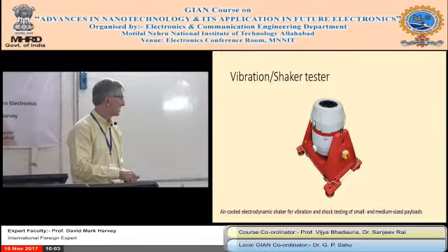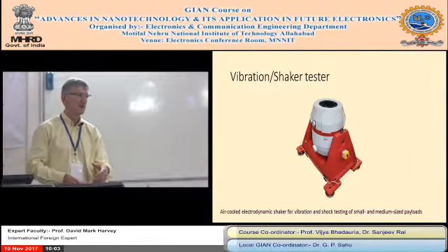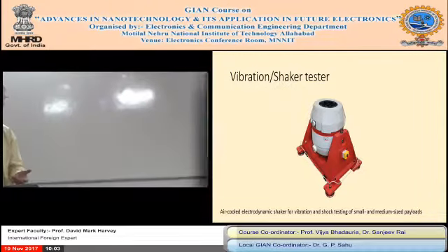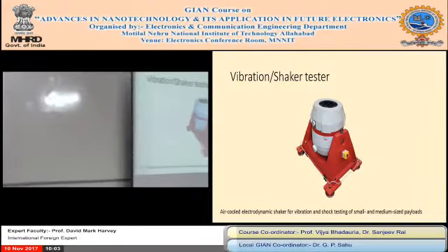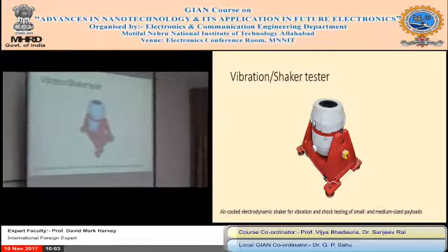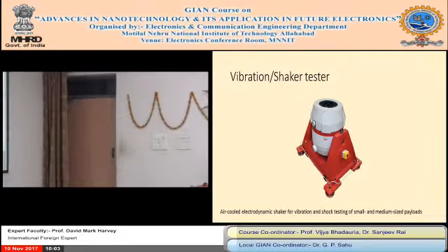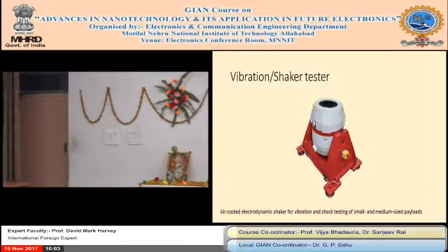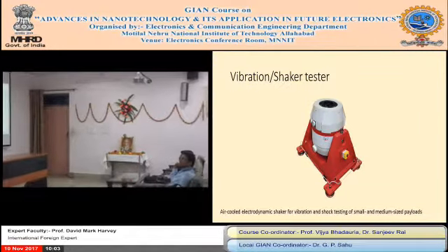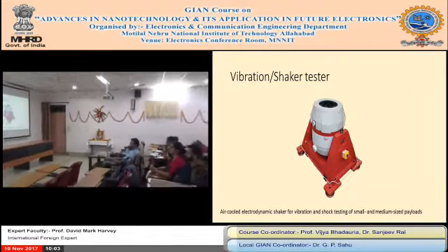So how it works in practice is you have a vibration profile based on where the product's going. A vibration profile for automotive will be different from, say, consumer electronics. And obviously you want to test it so that you've got an aggressive profile. So a lot of experience is required to do this sort of testing.